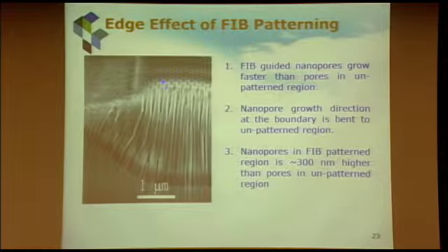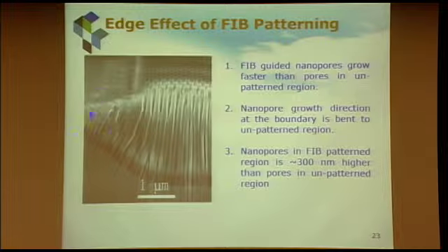So what we have found is that your patterning process, because we have this amorphization process for the matrix, gallium ion implantation, and so on, actually biases the process. The patterned areas tend to grow much faster. And because it grows much faster, it pushes the material away. So when these regions start to form pores, they are kind of lagged behind.